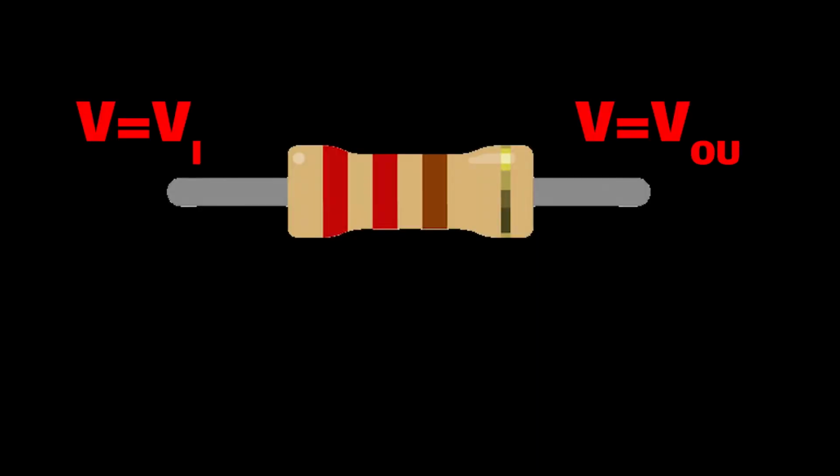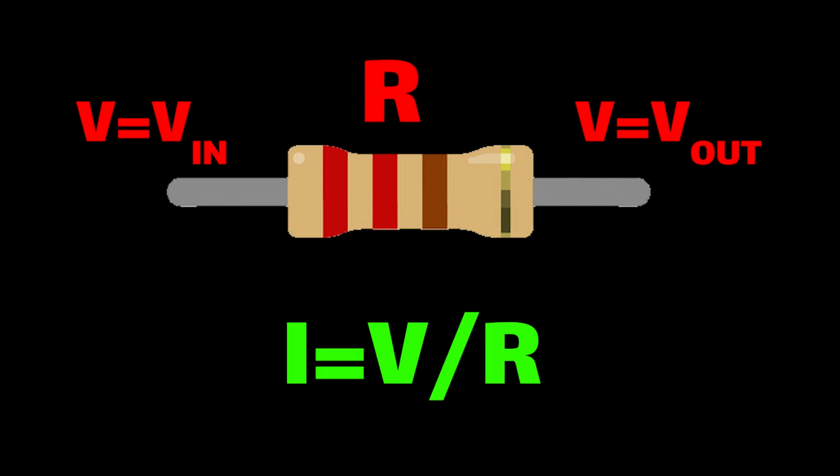Anyway, moving on, let's talk about another use for resistors that I know will be very helpful for beginners and will definitely open their eyes. I'm talking about using resistors for current measurement. For this, we need to revisit Ohm's law. We know that the voltage across a resistor is related to the current flowing through it and its resistance using Ohm's law. I mean this formula right here. Using this formula, if we know the voltage across a resistor and since we usually know the resistance, we can use this formula to measure the current flowing through the resistor. Anyway, up to this point, it seems pretty simple, right?